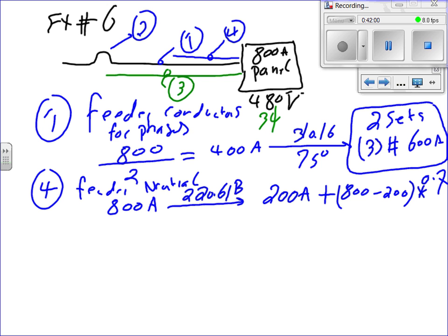So 200, how much? 620. Anybody? I need a lot of gentlemen to agree with 620 amps. I need another gentleman or a lady. 620. Okay. 2 gentlemen will never agree on something wrong. That's a rule. Okay, 620. Everybody knows what I did? I took the amps and cut them by 70%, anything higher than 200.